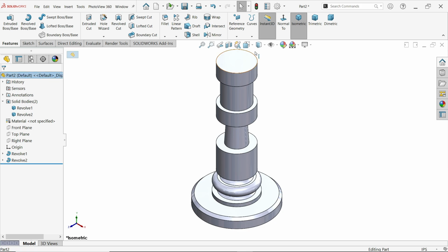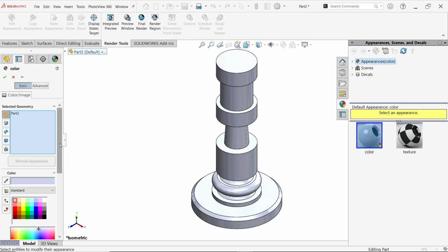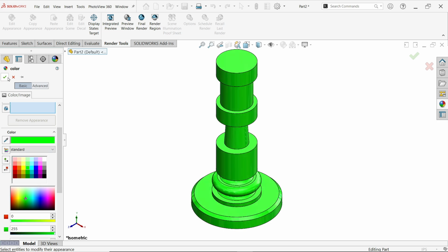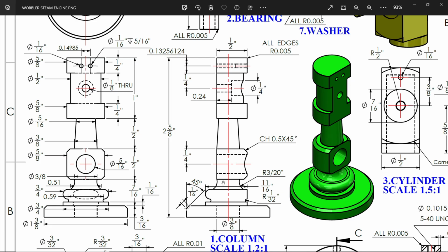Now let me do one thing, edit the color so that it looks more visible. Fine. Now you will see there is a cutout. This is the right face. You will see this in this side section. This is cut out up to here, 1/2. This is the cutting dimension. Then in the opposite direction there is one more cutout, 11/16. See, distance from here to here, 11/16, and this is going to be cut like this up to this face. You will see here in hidden line.